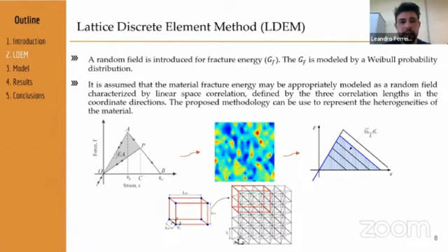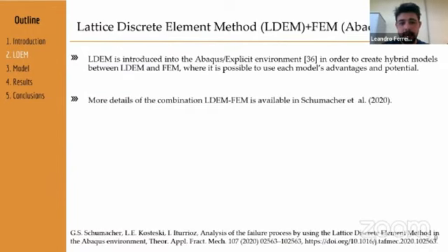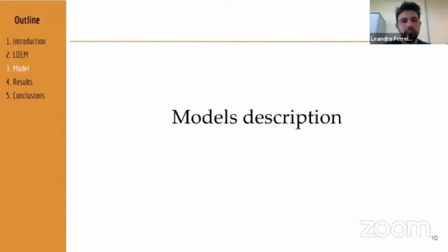The LDEM is introduced in the Abaqus explicit environment in order to create hybrid models between the lattice discrete element method and the finite element method, where it's possible to use each model's advantages and potential. More details about this combination are available in the work of Schumacher.